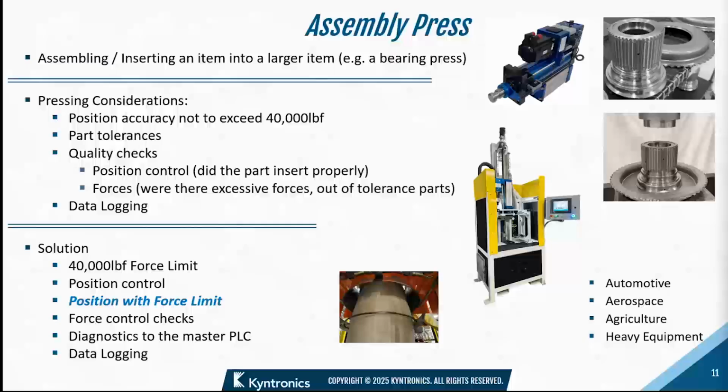So it'll protect the machine, won't damage the dies, won't damage the equipment or the actuator. And again, the control checks, go, no go type thing will be sent up. So that's the force limit. Again, it converts from position control to force control, bumpless, and it'll apply the force. So there could be other applications of presses that require that mode as well.